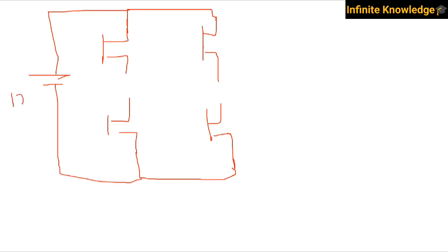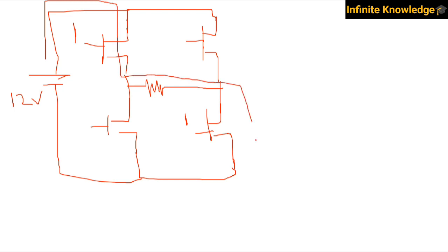So this is a battery, and these are some gate pulses to operate the MOSFETs. And here I can connect the output. Whenever these two MOSFETs, this one and this one, are activated, current flows from this part to this part. During this time, these two remain off.